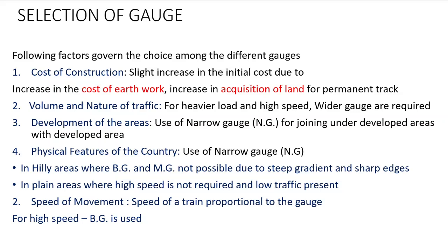Why may the cost of construction increase? If a broader gauge is used, the cost of earthwork will be more and also the acquisition of land will increase, and thereby the cost of construction will also increase. But it has a lesser impact among the factors which govern the selection of gauge.